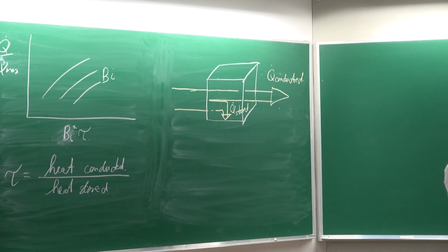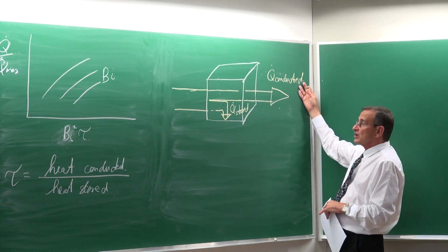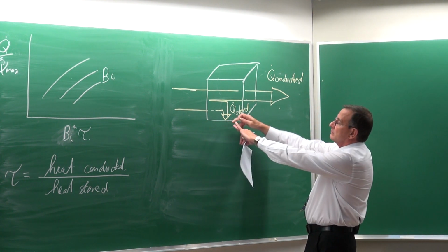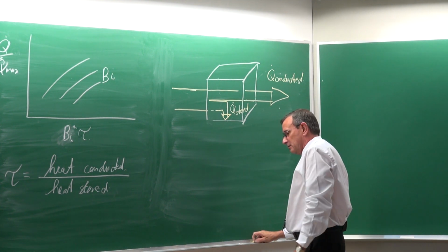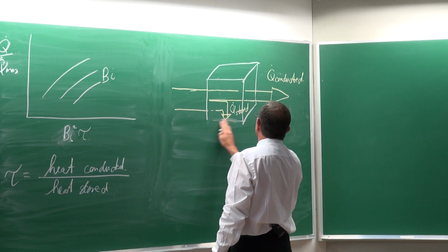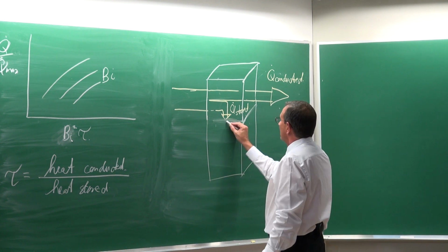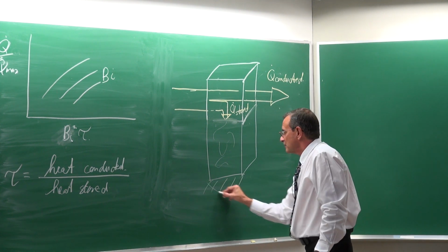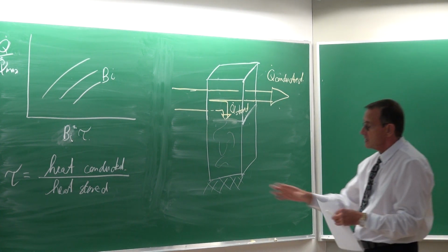Okay. It's like a tank of water with holes in it. The holes would represent the conduction heat transfer, where the heat transfer goes out or the water goes out. This, although the arrow is showing in this direction, maybe I should have rather drawn it like that. Much bigger body. Okay. And this heat is absorbed everywhere. It doesn't go out on this surface. So let's suppose that surface is insulated. Everything is being stored inside the body. So that is what the Fourier number represents.